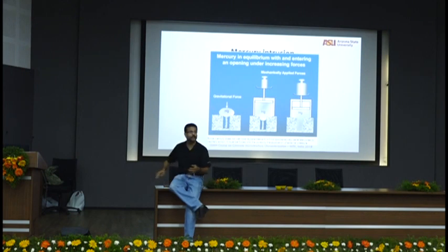There's a lot of variability between the specimens also. So in mercury intrusion porosimetry, even if you're applying this 440 megapascal stress, you will not have complete failure of these particles, because you have confinement from all different sides. You're applying pressure from all different sides. Basically, the idea is to squeeze mercury inside. You might have a few cracks, sometimes extra cracks formed when the load application becomes non-uniform. Sometimes that happens, but that is something that we will have to consider in the process.